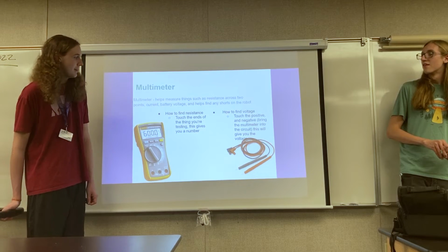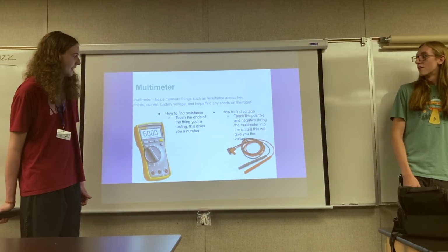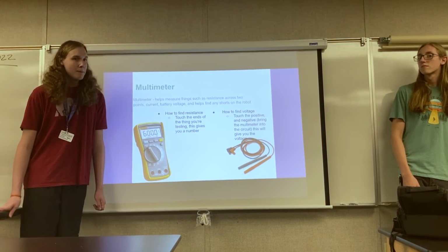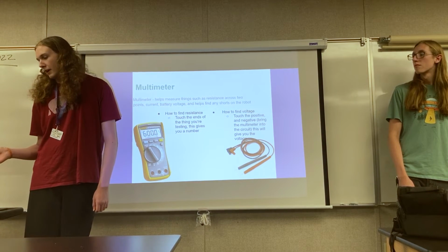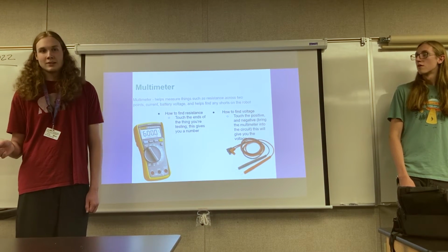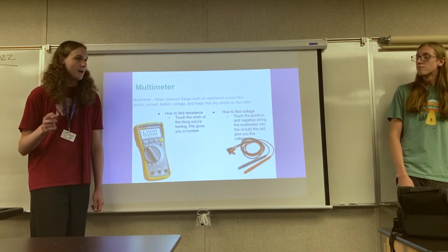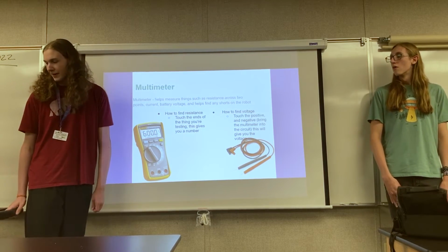So we use multimeters to find a lot of things, like the voltage of things, and to test the amperage of different things. But a useful thing is you can connect it to two ends of a circuit that you think is hooked up, and then it has continuity mode, which will beep if the signal is flowing all the way through it. So you can use that to detect breaks if things aren't working.